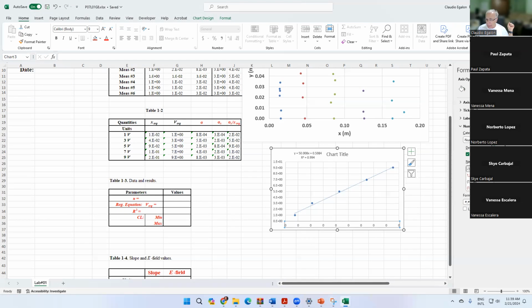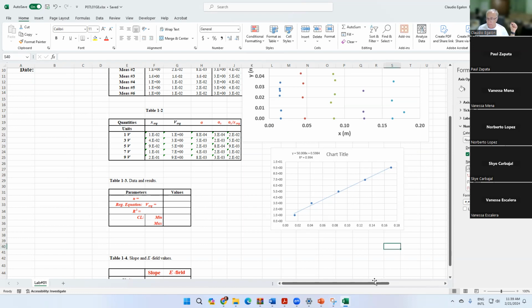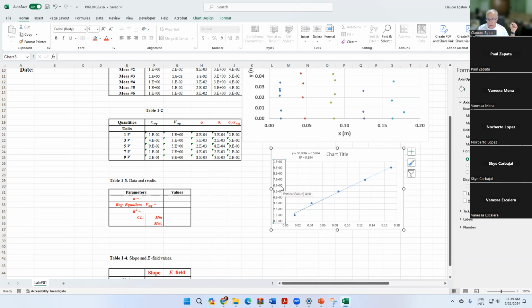And then we're going to add decimal places. I believe it's 2 decimal places. Yeah, 2 decimal places is a good one: 2 centimeters, 4 centimeters, 6 centimeters, and so on. And you do the same thing here. You do not need the scientific format. You can use numeric format. Numeric format is preferable to scientific. And just put 1 decimal place. We don't need more than 1 decimal place.